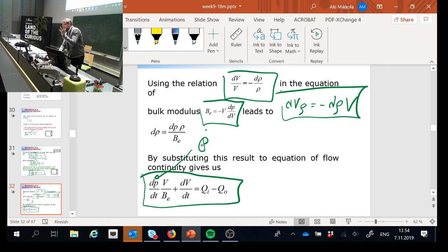It's the same as, remember, in multi-body system dynamics, we look at the x double dot. And from that we can get x dot, and from that we can get x. Same here, except that's where we're going to get started. So we're going to start from the P dot, and we're going to get P. And what's P? Pressure. Why do we want pressure? Because the pressure tells us how much force is produced by a cylinder or a motor.